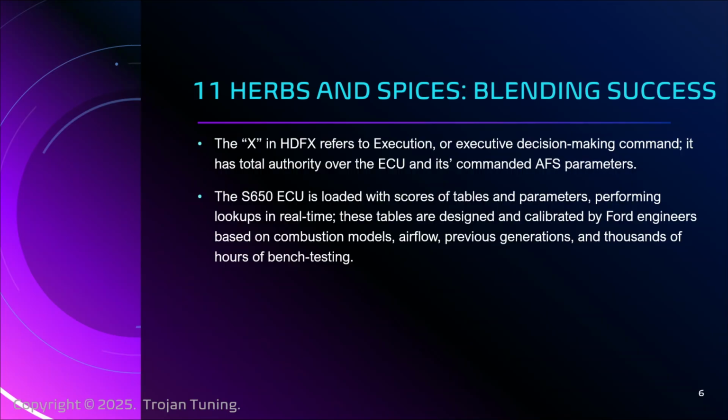So, how does it work? This thing is loaded with hundreds of tables, parameters, various lookups, all the different charts. If you've done any tuning before, you know there are a number of maps or tables that have all the different command parameters, and they're broken out by things like, in speed density tuning, right? We have our pressure down one side, we have our RPM down the other side, and in the middle is the ideal state of volumetric efficiency. And where I know volumetric efficiency, I know the fuel that I need to have, right? So that, amongst other things, it's constantly looking up things that are stored in static tables.